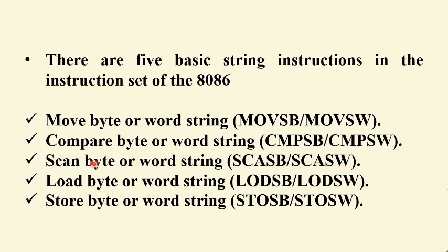And similarly to load the data, suppose we have to load a byte string, we will use LODSB, and to load a word string we will use LODSW. Similarly for store, STOSB and STOSW. B is for byte, and this W is indicating word.